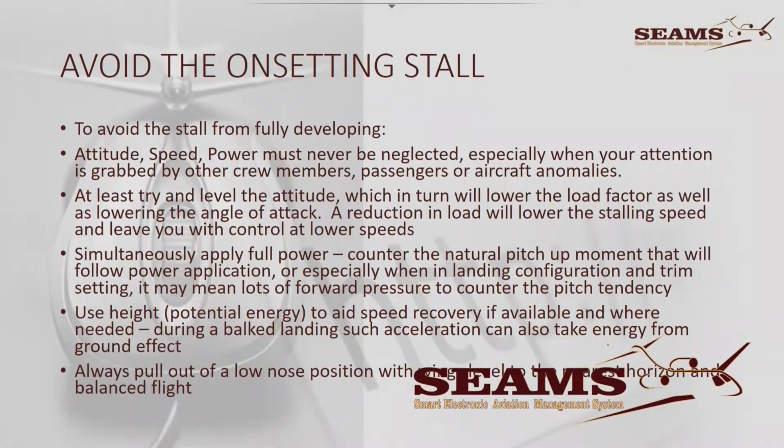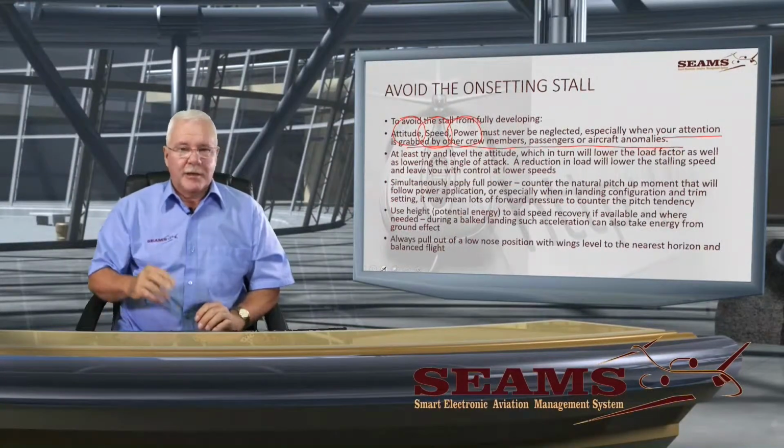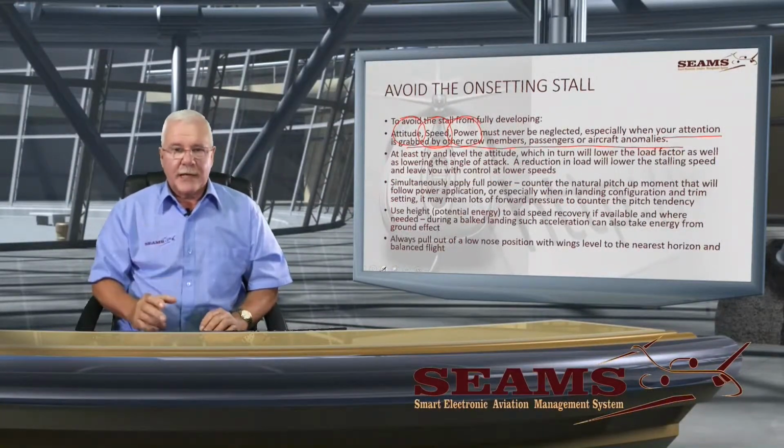Now, how do we avoid the onsetting stall? To avoid a fully developing stall, watch the attitude, which relates to speed and power. When your attention is grabbed by your crew, passengers, or aircraft problems, you cannot stop flying.